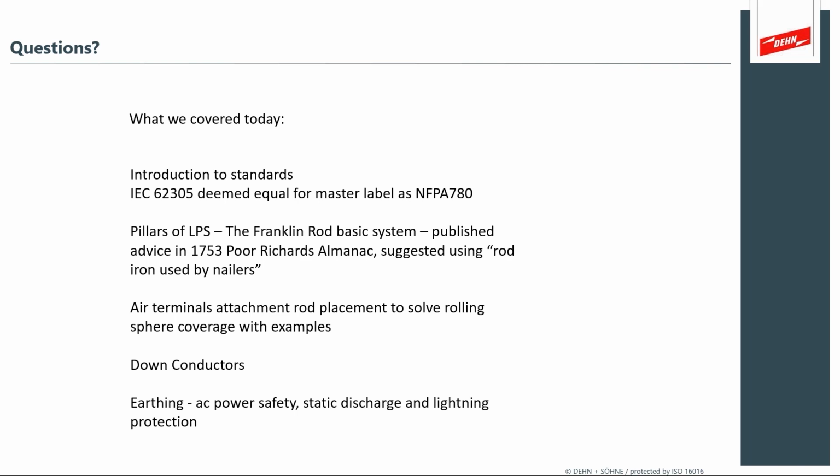And that's similar between NFPA and IEC methods. Yes, yes. But for an oil tank application like that, you have to pay a lot of attention to the earthing system, because the tank sits on the ground. There might be a membrane to prevent it from leaking, and now you really have to pay attention to how well that tank is physically earthed into the system. Yes, agreed.